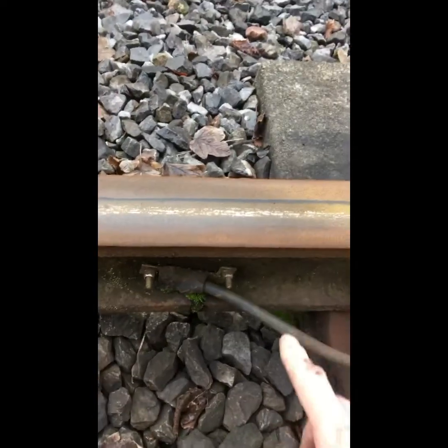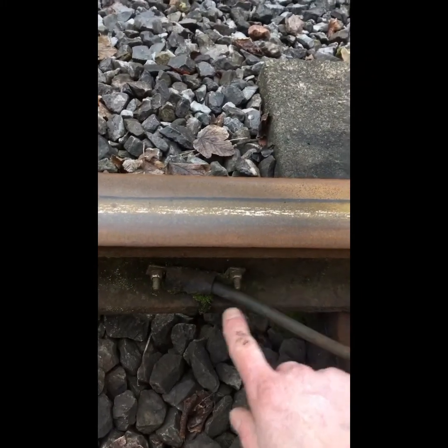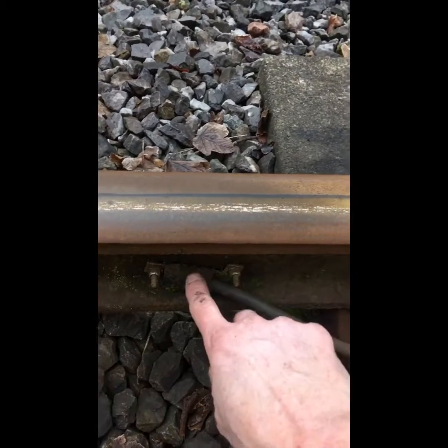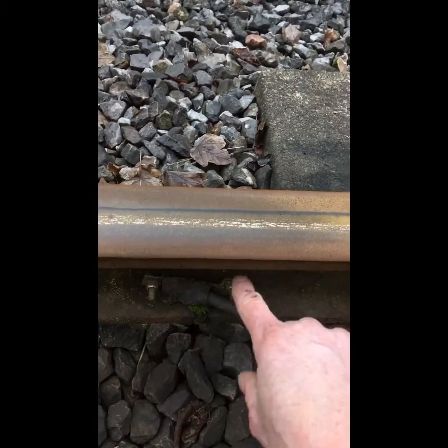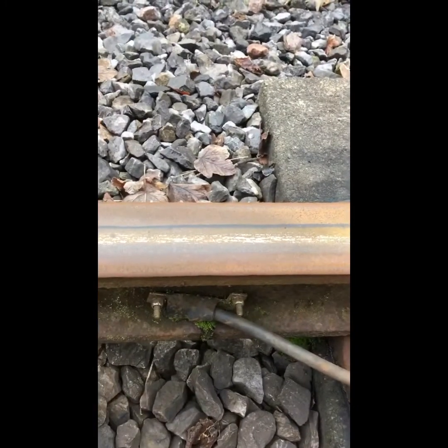And another way, which we used to do, we used to just drill the holes through the rail, put a piece of bond wire through, two bond pins on the opposite side, and we used to just solder this on. We used to call that goal posting, because it looks like a goal post. That's an older way of doing it. But there are various different ways of doing it.